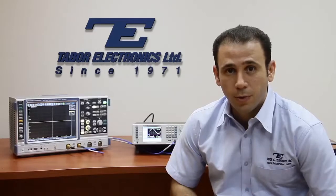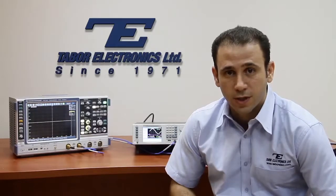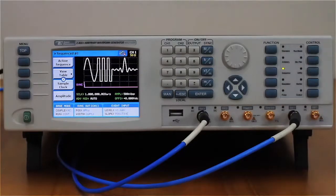The first step to build a sequence is to download your waveforms into the different segments, or to split a large waveform into several segments. Once that's done, we can build our sequence. To begin, press the Sequence button in the Function menu. A new set of menus appears on the screen.